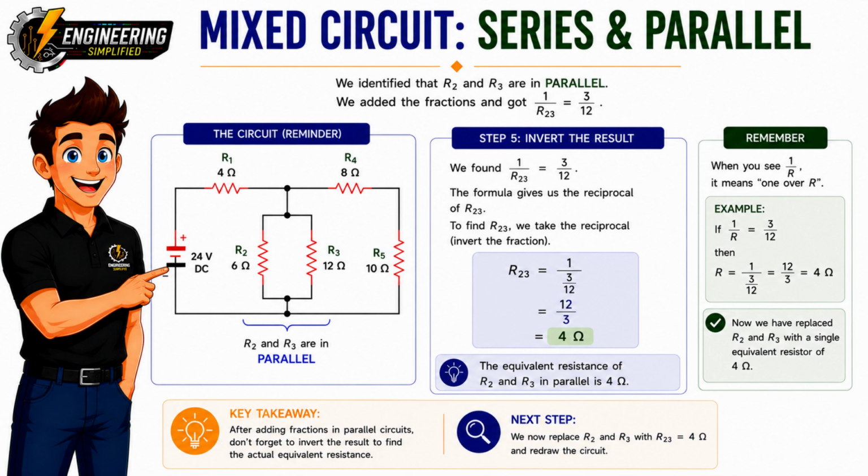This means the two parallel resistors, R2 and R3, can now be replaced with a single 4 ohm resistor that behaves exactly the same as the original parallel combination. This is a major milestone because our mixed circuit has just become much simpler. In the next step, we'll redraw the circuit using this new 4 ohm equivalent resistor and continue reducing the circuit until we find the total resistance.